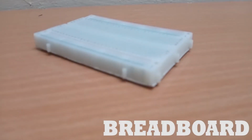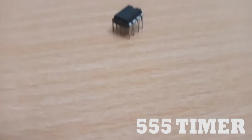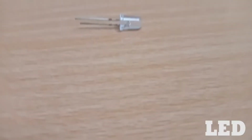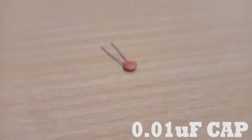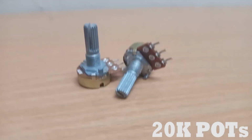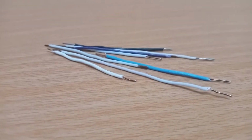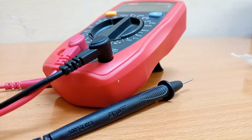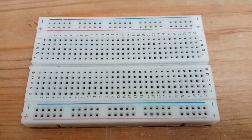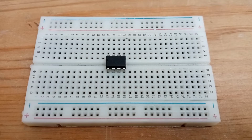To build the circuit, we need a breadboard, a 555 timer IC, an LED of any color, a 47 microfarad capacitor, a 220 ohm resistor, a 0.01 microfarad capacitor, two 20 kilo ohm potentiometers, some connecting wires, a power supply, and one digital multimeter. After setting up the breadboard, the timer IC goes to the middle of the breadboard.